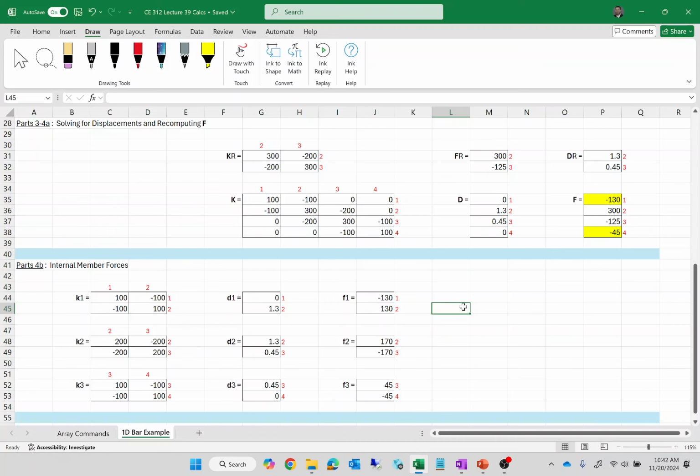So, let me give you an example. What is the difference between what we've been doing now and trusses? I'll give you one answer: trig. I kid you not. The only difference between this problem and a truss analysis is the inclusion of trigonometry. That's it. If you understand this, you understand how to do a truss problem. And we're going to talk about how to extend this to a truss analysis when you come back from break.